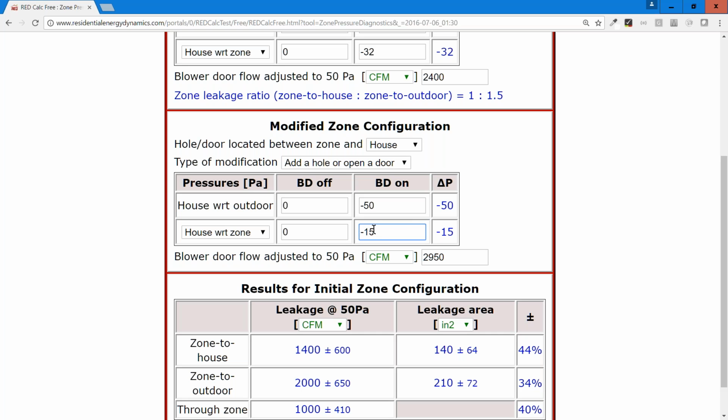So if we opened another attic hatch, if there were one, this value would go down because we would make the attic floor even leakier. So we'd have a greater difference between the 32 and the 15. We'd have a 32 and a 10, for example, which means the accuracy here would go up. So this uncertainty number would go down. We are reporting uncertainty so you learn out in the field when you're using this tool what you can do to make your results more accurate.